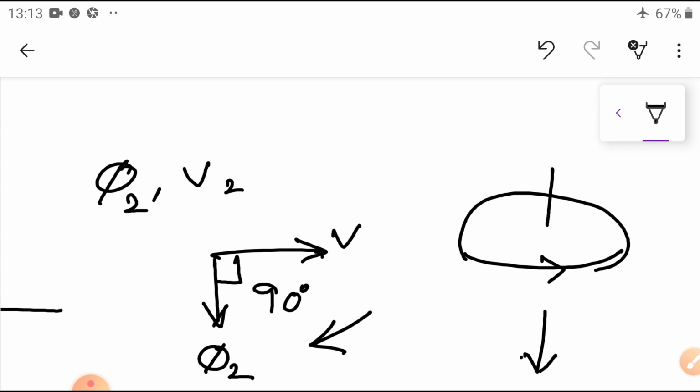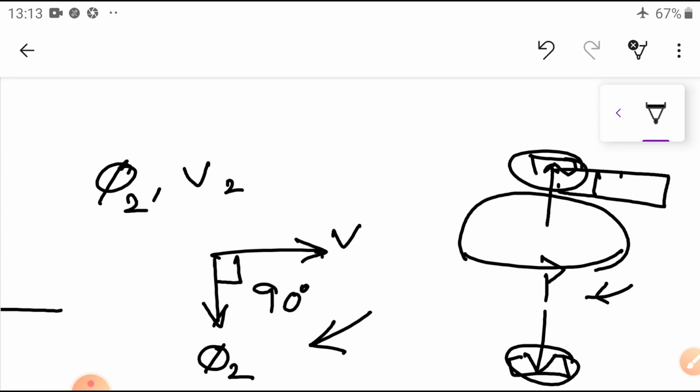We are going to provide on the bearings. So it is possible that friction takes place in the bearings itself, thereby the rotation of the disk will slow down. So that can be one of the errors that may occur. At the same time, this spindle is also connected to the gear mechanism with a worm, where it registers the numbers. So due to this friction, the speed of our disk also slows. That is the friction error.